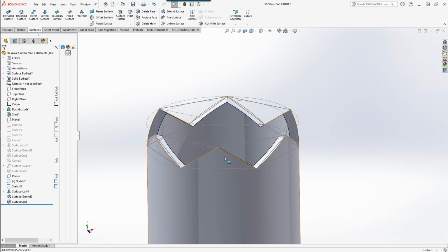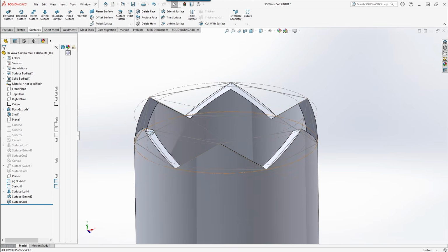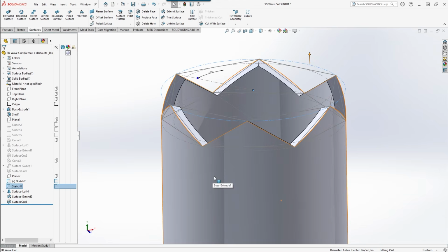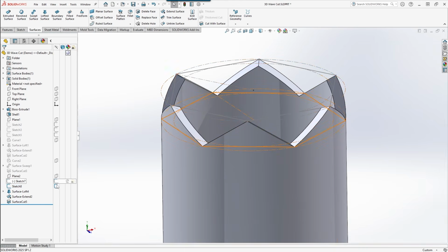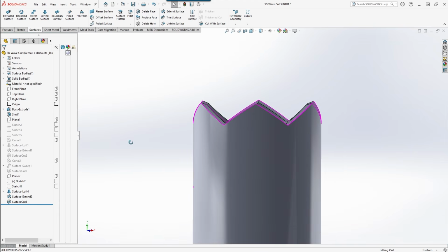Now, with that in mind, as you can see, mine is the version that has the angular top, and it extends down to the center of the lower plane. All you have to do for the opposite is take this plane on top and make the point that it's going to extend down to from this top plane, and then send it out on an angle to the bottom second plane. So it's basically just reversing the two planes that we used. Not very difficult. So that's how we do the jagged cut, and then we can hide all the sketches and the reference geometry, so you can see how that looks.